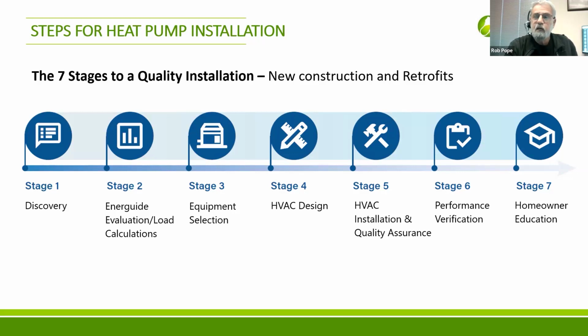If you're not doing any other upgrades to that house, and if it's an older house, that's probably a leaky house. You wouldn't know that unless you did a blower door test. You wouldn't know precisely how leaky it is. But if it's a drafty house, your HRV is not going to do you any favors. It's not going to do anything. It's just going to be moving air in and out of a building that's already moving a lot of air in and out. It's not going to save any efficiencies.